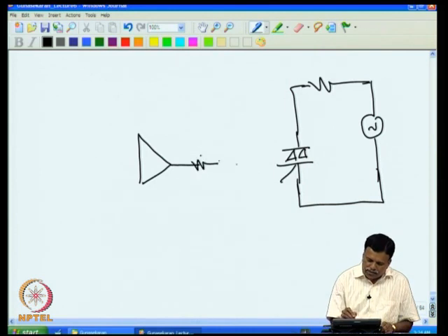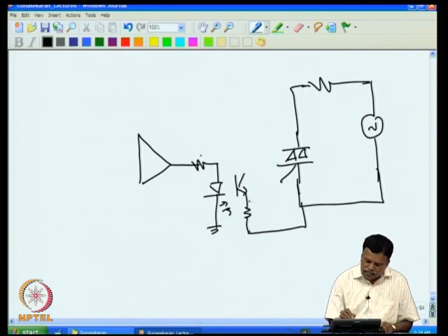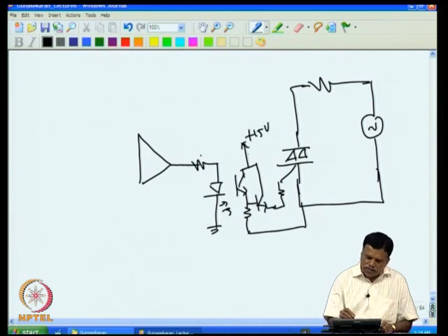Now instead of giving it directly to this, I can connect it to the opto isolator's LED. That can be connected to the other side, which we had done earlier, and that is the plus 15 volt, whose ground is this, not the ground of this. So you have an isolated plus 15 volt that will drive the opto isolator. That way the isolation is provided.